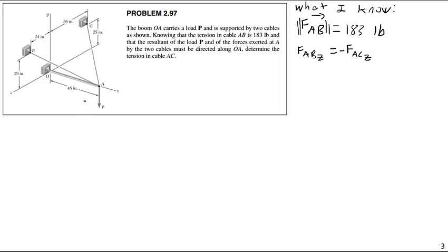Is it keeping the rod straight and not moving to one side or the other? This is a statics problem. Yes, it's not moving whatsoever. Could you say that it's in partial equilibrium? No, it's in complete equilibrium. But doesn't the resultant go along the rod? No, because this thing is going to have a force, and we could calculate that. What this is just saying is that this rod will not carry any Z or Y directional force. It will only carry X force. Okay, so let's consider that then.